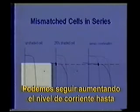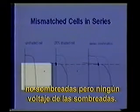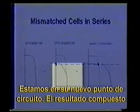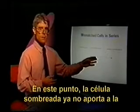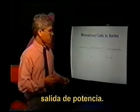We can continue increasing our current level until we get to a point where we get voltage contributed by the unshaded cell, but no voltage contributed by the shaded cell. We're at its new short circuit point. The composite result is simply the result of the unshaded cell. The shaded cell at this point is no longer contributing to the power output of the string.